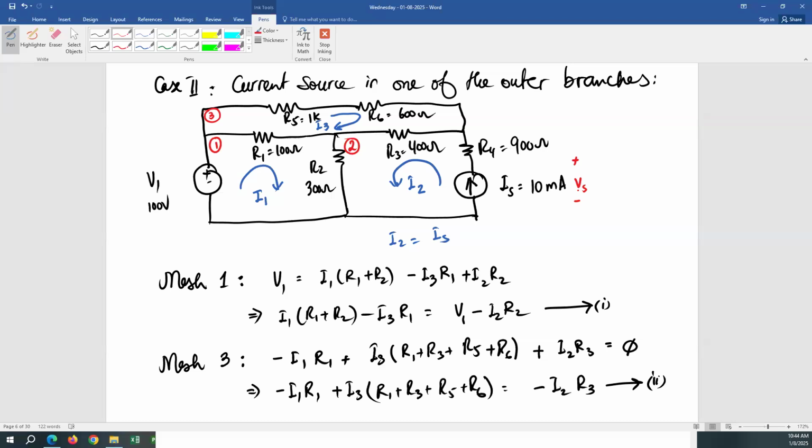All right. How about using the node voltage method that we just discussed? Can we do that? Since we know all the current values and all the resistor values, can we calculate the voltage? Assume that the bottom is ground. Can we calculate the node voltage here? That will be the voltage across the source. And once we know that node voltage, we can calculate the power, right?